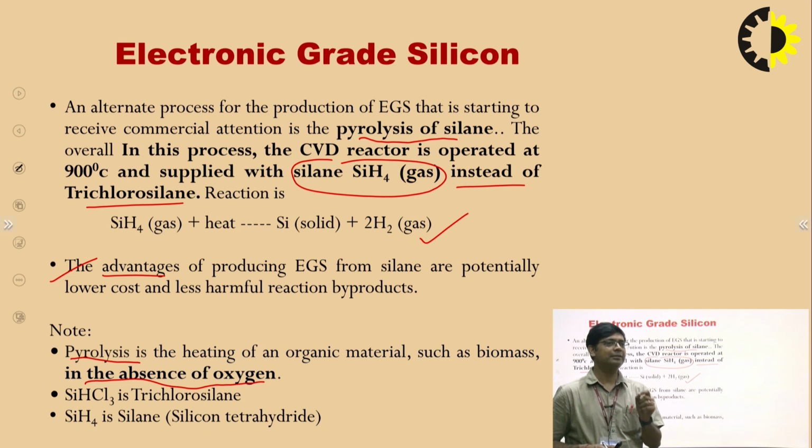First of all we have to get the trichlorosilane from the MGS silicon in the fluidized bed at 300 degrees centigrade, where the reaction takes place with HCl, and then this trichlorosilane is purified using the distillation process, and then this purer trichlorosilane is given as a raw material to the CVD reactor, where we use a slim rod which acts as a nucleation point, and across this slim rod the silicon gets deposited, and its diameter can be as high as about 200 millimeter, that is 0.2 meter.